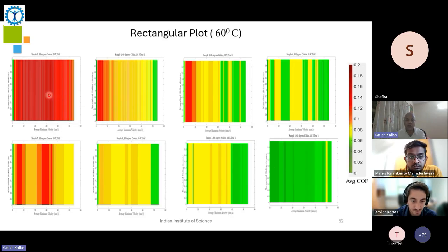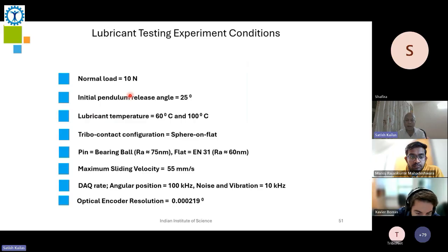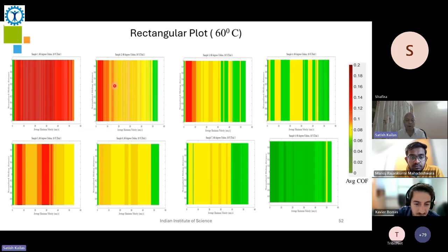So, for example, base oil 1, the lower cSt one, is not as good in the boundary lubrication regime, whereas base oil 2 with higher viscosity is better as a boundary lubricant when it is added plain. But when I take these and use the anti-wear and all the other additives, I can see that base oil 2 is much better than base oil 1 plus the additives.